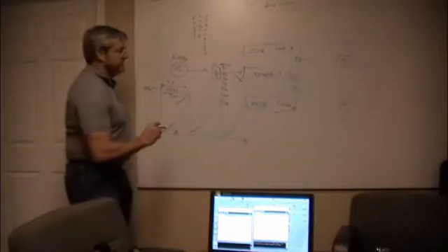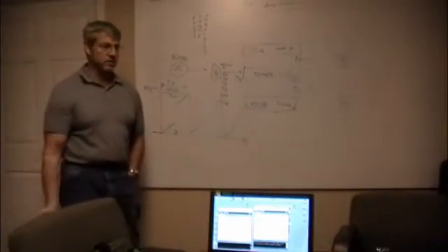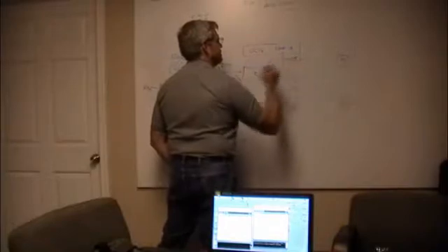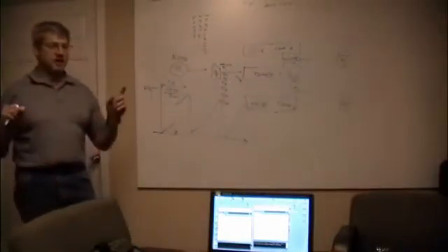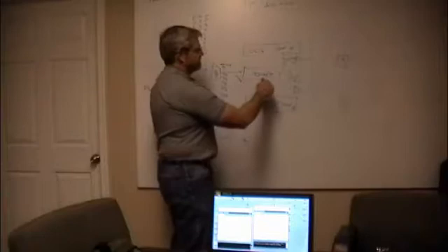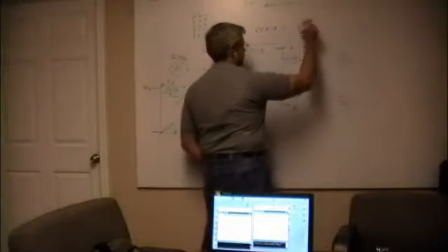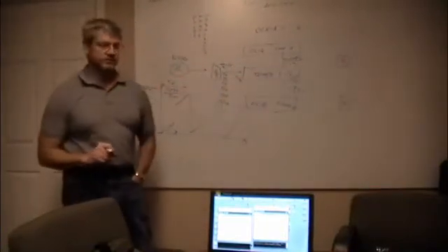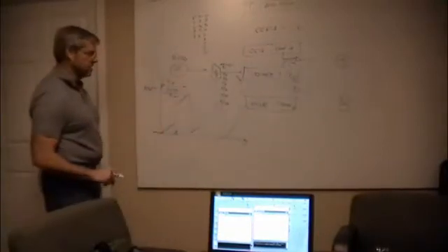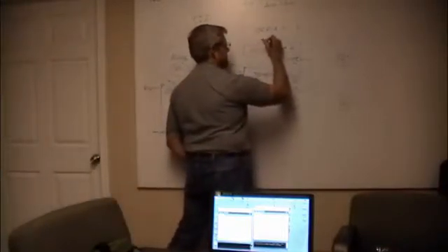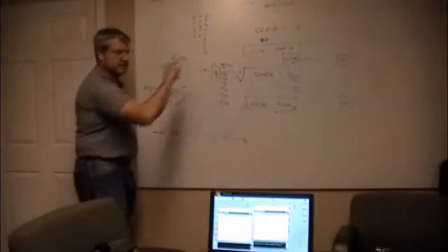So now I have some choices with my timer hardware. I can say anytime that this and this, that's an AND symbol, anytime they are the same, I can make something happen. So in my hardware, I don't usually diddle timer 1, but I can write in my C code, OCR1A equals some value. And it will write it directly into that specific piece of register hardware. So I can say, if this is equal to, let's choose an easy number, 8K, since that's half. So whenever this is 8K, I can tell it to toggle that bit.